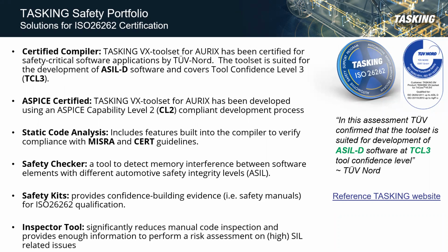Talking a little bit more about the inspector tool, benefits include that it inspects your complete project in one run and provides guidance if a patch is needed or not. It reduces time and the variability associated with manual checking. It's fairly easy to use with minimal integration effort, usable within the makefile. And again, it warns if compiler output is impacted by SIL 2, 3, 4 issues, which are published on our issues portal. So if you're doing ASIL development, it's probably something to look into in the near future.